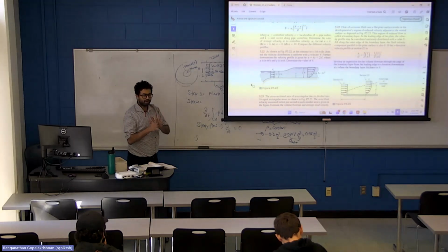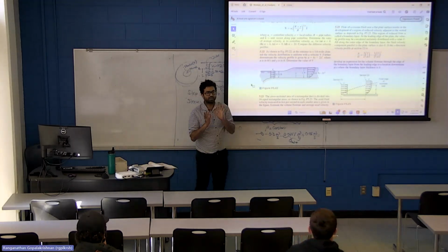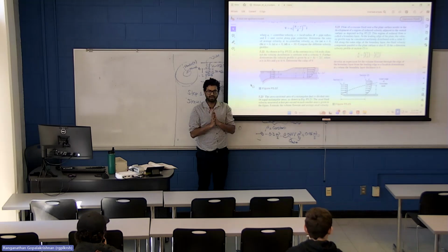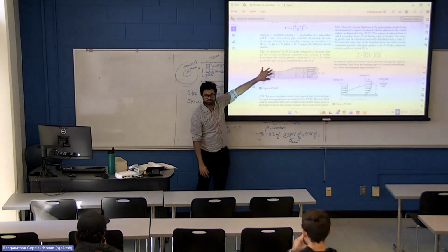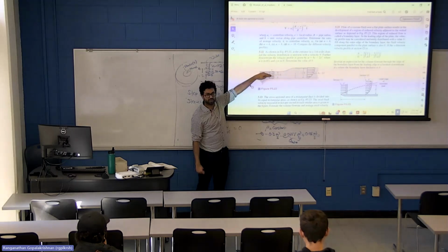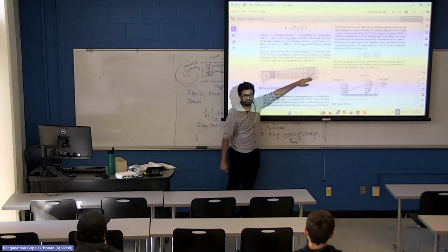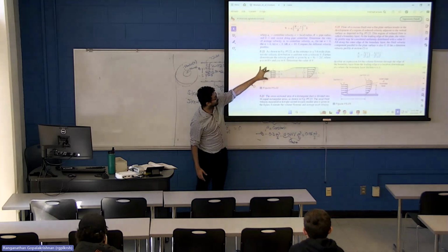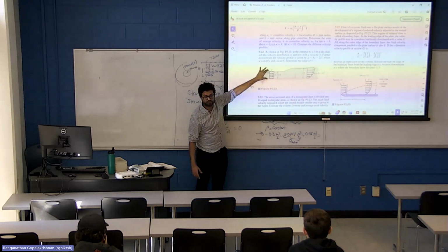Take a moment, look up. Don't think of this problem. I mean, in this mass balance, don't get too bogged down by mathematics. Think what's happening intuitively. This is water, incompressible. If water comes in at a certain flow rate, it has to leave at the same flow rate if it's a steady flow, right? So if you compute what's the flow rate coming in, what is flow rate?